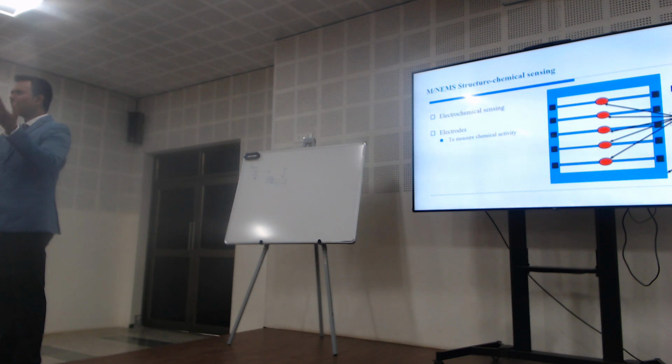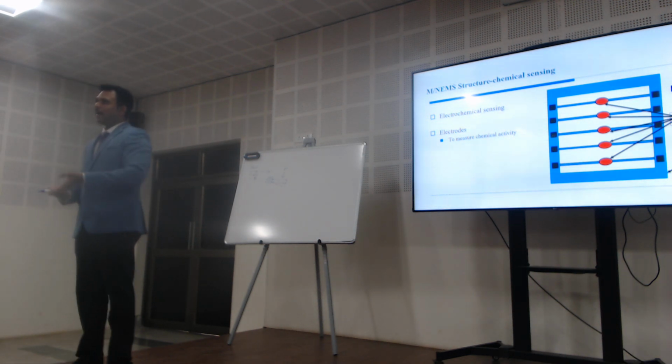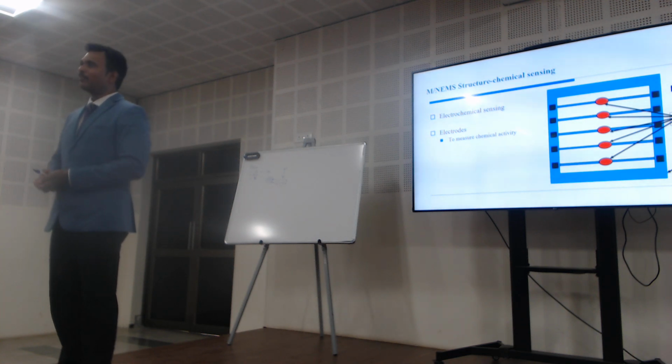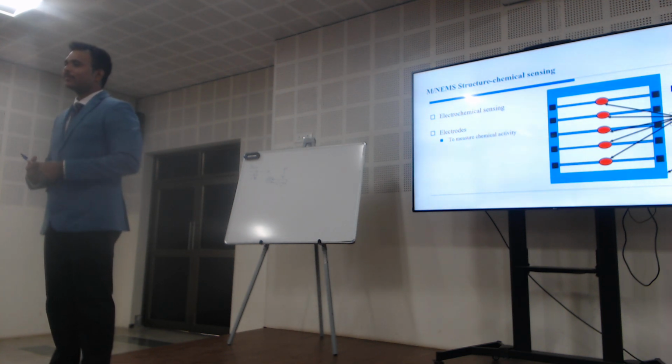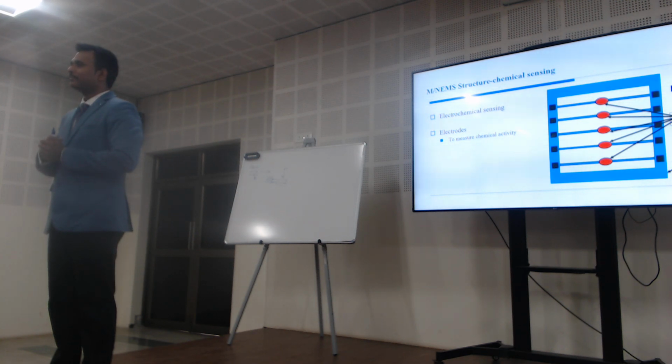For all movable sensors, for change of capacitance, we can directly take silicon. For piezo also, directly. Have you worked with MEMS or not? Maximum 90% of all movable sensors use capacitance, not piezo. Why? Because of sensitivity. Only because of sensitivity.